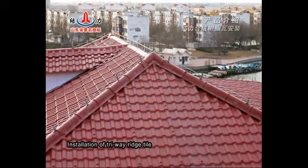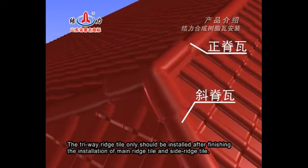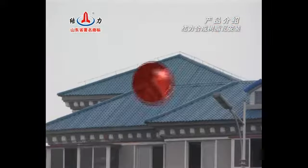Installation of tri-way ridge tile. The tri-way ridge tile should only be installed after finishing the installation of main ridge tile and side ridge tile. The horizontal side should be on the top of the main ridge tile.